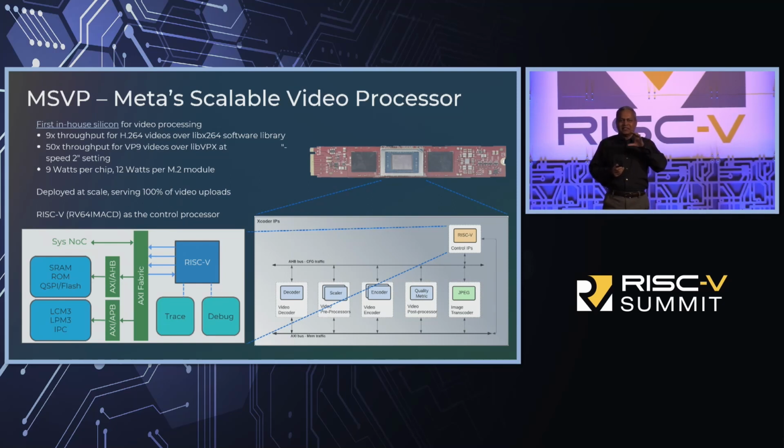So all the scheduling between all the functions within the video transcoder core, as well as realizing some of the video transcode function itself, is all done on the RISC-V core. And this is the one that is really creating a hardware abstraction layer for our API, for all our video applications running for Facebook, Instagram, WhatsApp, Messenger, or whatever.